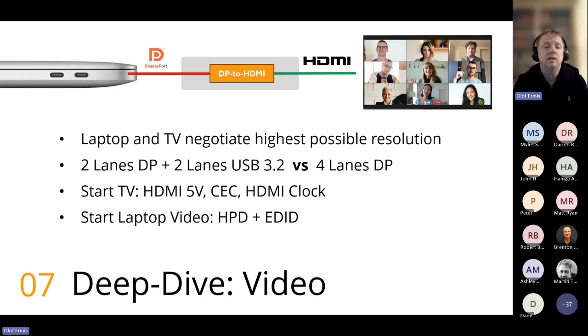Normally in a new laptop, that's 2 lanes, each at 8.1 gigabit, what is called HBR3. So the laptop will then have 16 gigabit of bandwidth available for video. If you have HDMI 2.0 on the other hand, you have 18 gigabit there, so that's fine. You can run all your resolutions, up to dual screen 4K 60 Hz with max compression and so on.